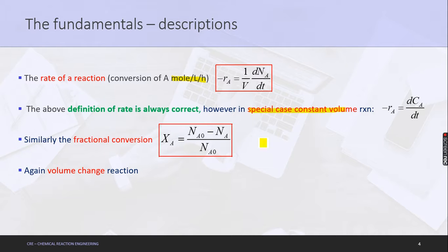And if we are going to talk about volume change in a reaction, then we need to understand eta A. Eta is going to give us the idea of how much volume change will happen once the whole reaction is complete. I mean to say, when XA equals 1, when complete conversion of one reactant to product has happened, then what is the final volume divided by the initial volume? So that is the fractional change in volume. When XA equals 100% conversion has taken place, that value is the fractional change in volume, or eta A.